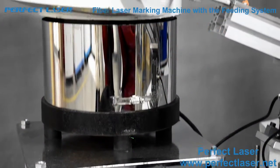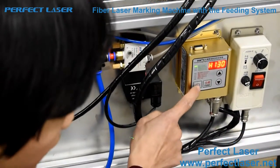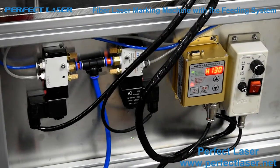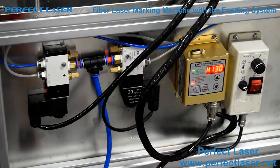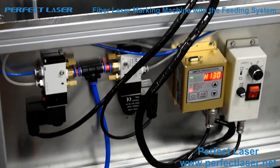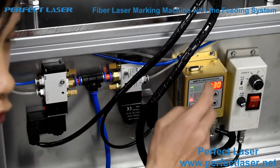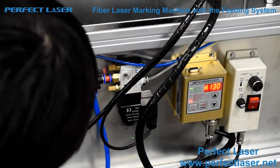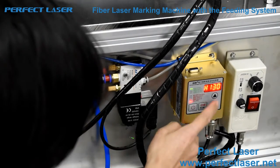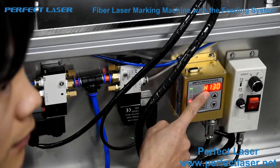The panel also gives indications. When it stops, the red stop light is on; when it is running, the red light is off. There is a small display showing H130, meaning the vibration frequency is 130, which is the speed of the feeder. You can adjust the speed with the up and down buttons.